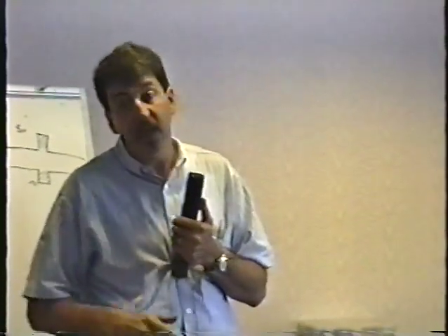Well, there's 3 of us that do field service at area amusements, and the communication between us is not all that good necessarily. So we get a service call on this Chase HQ, and the complaint is the picture is rolling vertically. Serviceman A goes out there. Yeah, it's rolling vertically, no problem. He takes the back off the game, adjusts the vertical hold control, solid as a rock, buttons it back up, leaves. Next week we get another service call, same complaint. But now Serviceman B is on duty, and he doesn't know Serviceman A has been out there to do the same thing. He goes out there, it's rolling, he takes the back off, he adjusts the vertical hold, everything's fine, he buttons it up, he leaves.